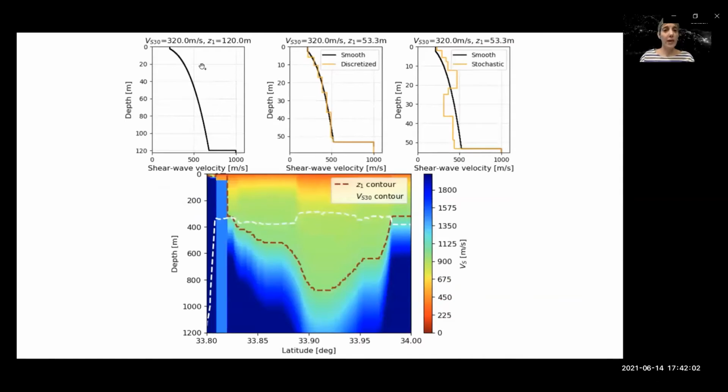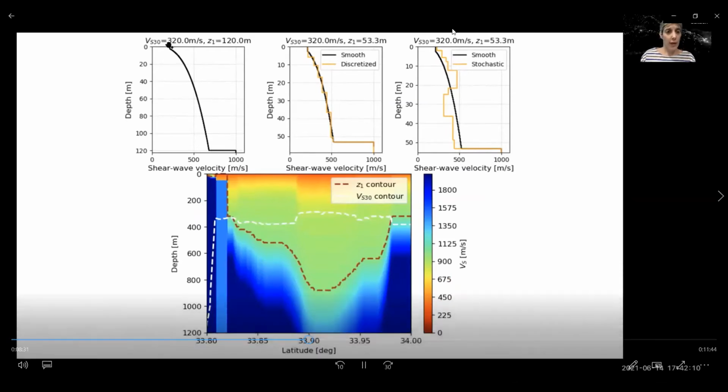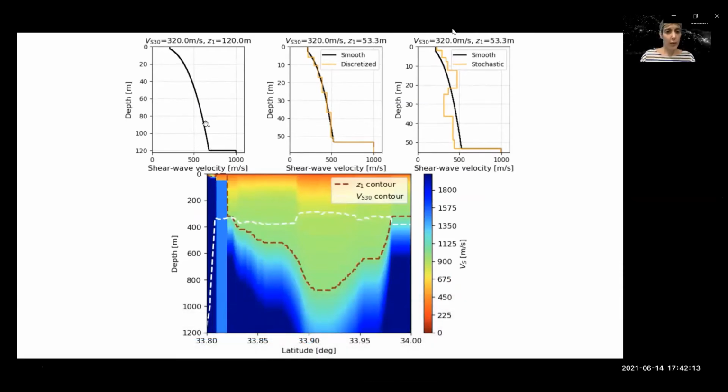So how SVM works: given a VS30 and a Z1000, the depth to 1 kilometer per second, the variation of the shear velocity is shown here, smoothed. We stop at Z1000 and we let whatever material properties the community velocity model has, the background, take over.